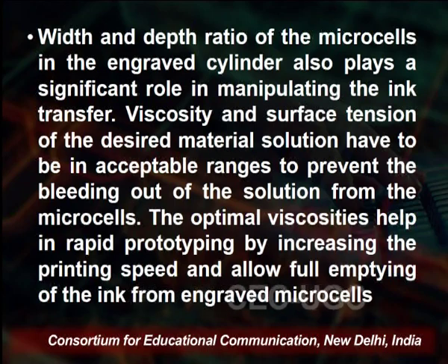Viscosity and surface tension of the desired material solution have to be in acceptable ranges to prevent the bleeding out of the solution from the microcell. It means the imprint should be neat and clean, with no extra ink flowing on the substrate.